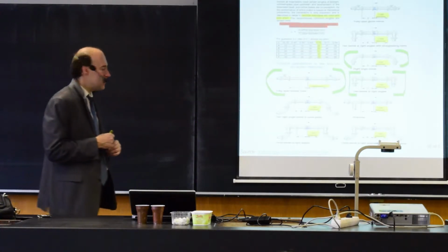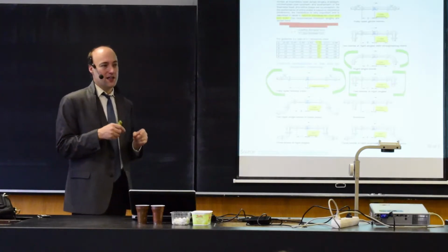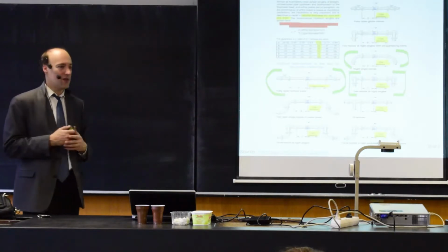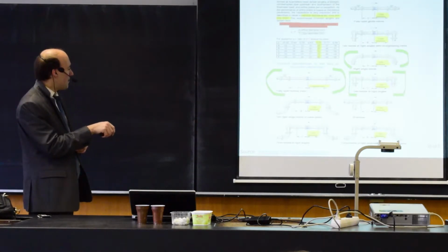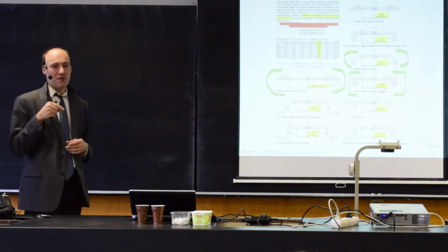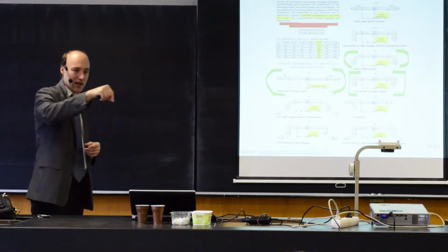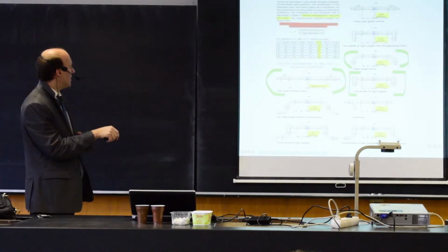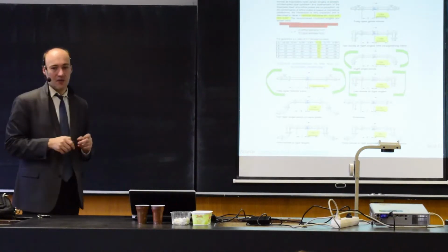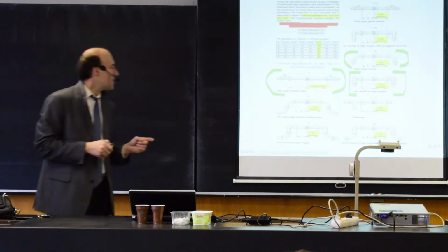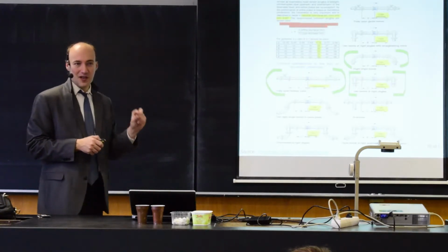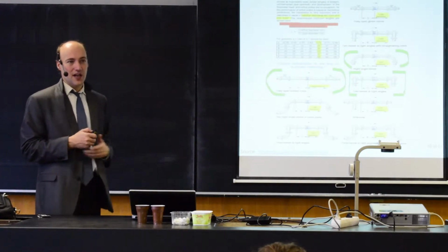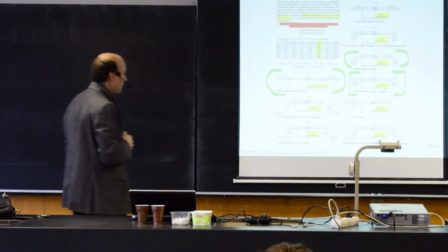So in many cases, it's not even possible to find a section in the piping that is straight and that does not have anything that prevents the flow. For example, in this case, you have a 90-degree bend in 2 directions, so like this and down. And here you see it's this line C, and you have 63 pipe diameters. So for 1 centimeter pipe diameter, you need to keep 63 centimeters in front of the orifice plate.